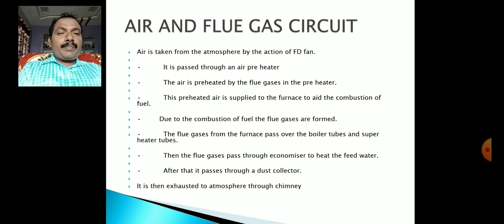So if you supply cool air, what happens? The cool air decreases the performance of the boiler, and it decreases the overall performance of the plant. That is the problem. So if preheated air is supplied to the furnace, the combustion efficiency increases. Due to the combustion of fuel, the flue gases are formed in the furnace.